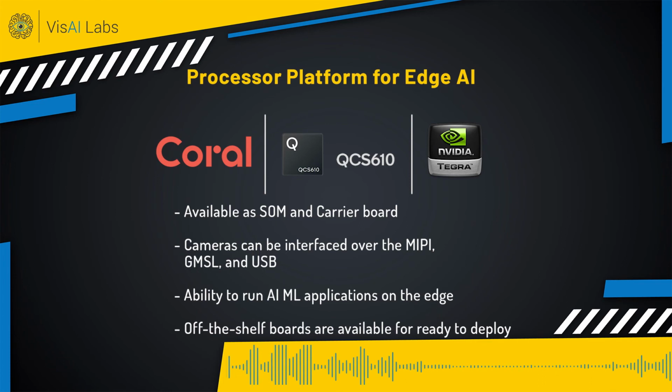These are the most popular edge devices. Okay, so you have special cores here for running your algorithm on the edge itself. The first one is Google Coral. It is actually based on the NXP IMX8 processor, but it comes with a Tensor Core chip, which can be used for edge AI processing. Google provides this SOM. This SOM is still in the early stage. We are supporting MIPI cameras for it already.